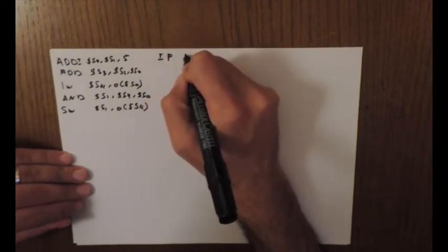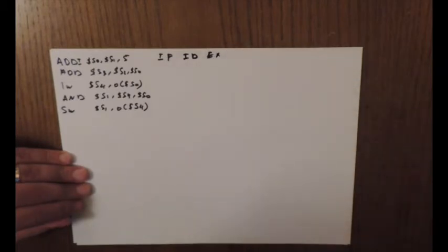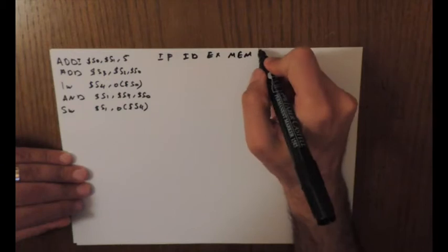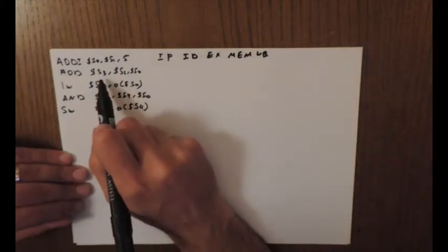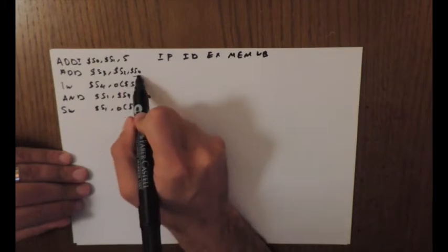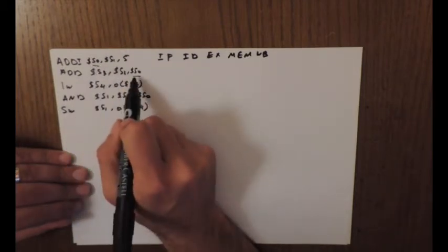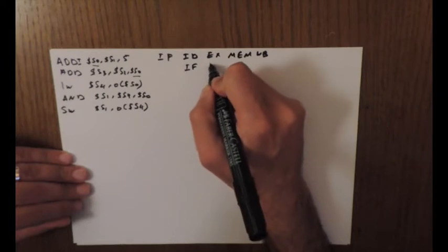Of course here we go directly, we have no dependency since it's the first instruction, and then write back. Now we look at the second instruction. We notice here that we have a dependency between the RD and the RT of the next instruction. So we look to see if forwarding will help.